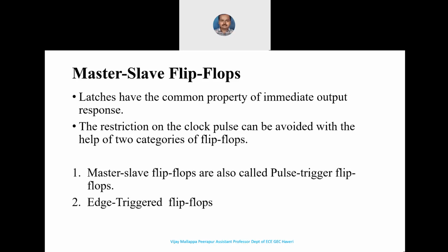I explained that when the propagation delay of the flip-flop is less than the width of the clock pulse, we have this condition, and we call it a race around condition. Everyone note this down. This is called a race around condition, right? To overcome this, I said one of the restrictions we can have on the design is that the propagation delay should be greater than the width of the clock pulse. That is a restriction so that we don't have the race around condition.